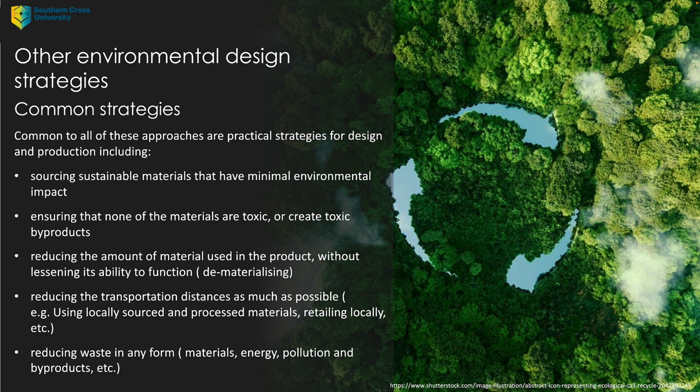Now we'll look at some common strategies, and these are common regardless of the material that we're using. And then later on, we're going to look at some of these again, but from a perspective of timber. So common to all of these approaches are practical strategies for design and production, and they include sourcing sustainable materials that have minimal environmental impact, ensuring that none of the materials are toxic or create toxic byproducts. So for example, some manufactured boards from the timber perspective have some glues or fillers in there which do not biodegrade well in landfill.